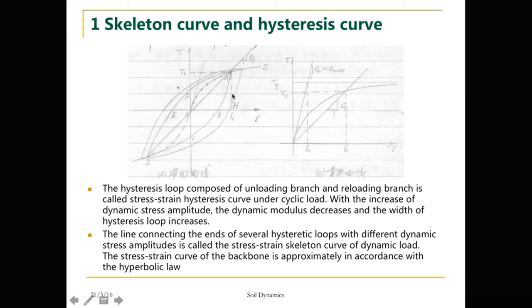Now let's see, from the initial condition, which is the 0 point, we apply the load on it, it will deform along the skeleton curve to a certain stress level. Then unloading occurs. Then it will deform following the unloading branch to the inverse point, the unloading stage ends and the reloading stage starts.